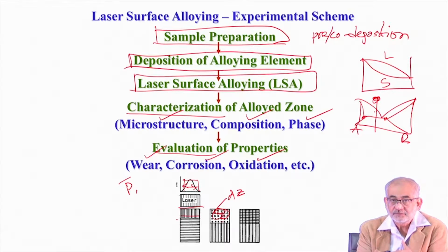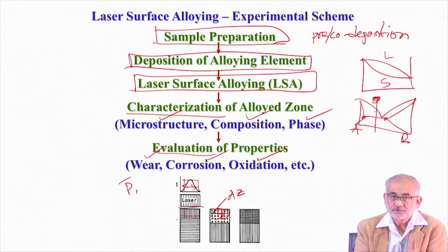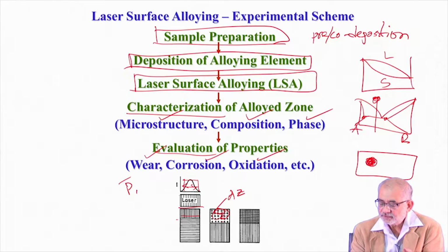And instantly they can form a very homogeneous alloy melt pool, because the volume that we are talking about is very, very small. And at that high temperature, because of the laser fluence and temperature gradient, you also have a good amount of convective mixing, also solutal diffusion in the liquid state, which is faster. So because of which, on this substrate, if this is the melt pool we are talking about, and this is probably just 1 or 2% of the total surface area, in this small area, instantly we mix A and B or A, B, C, and instantly we form an alloy of fairly homogeneous composition.